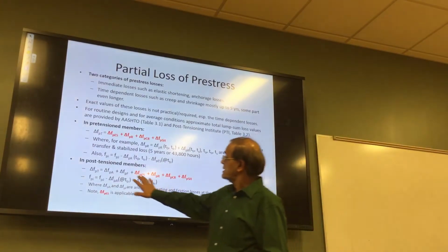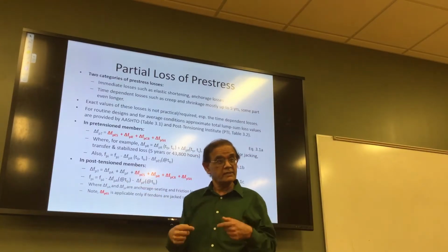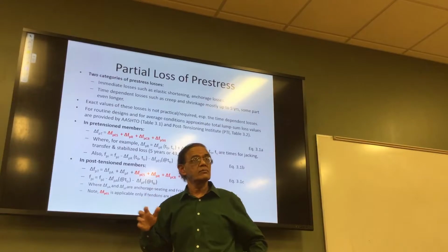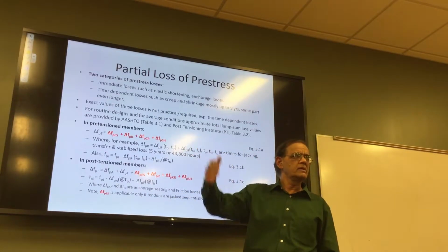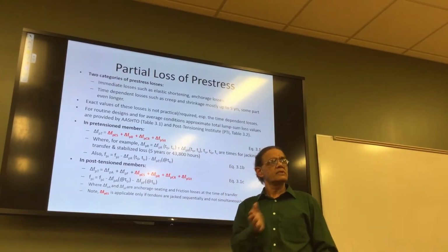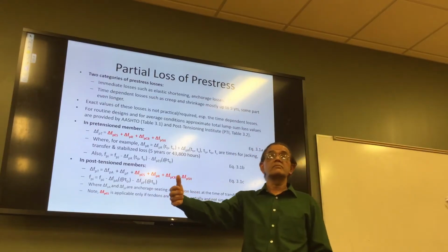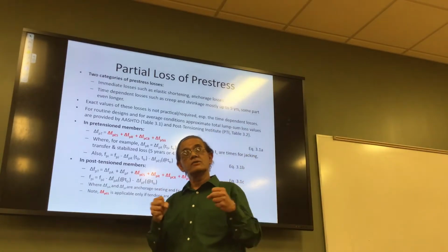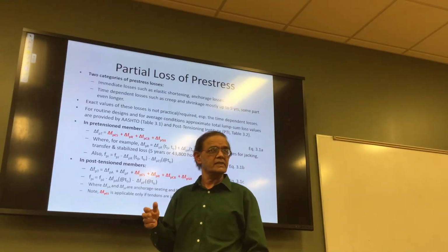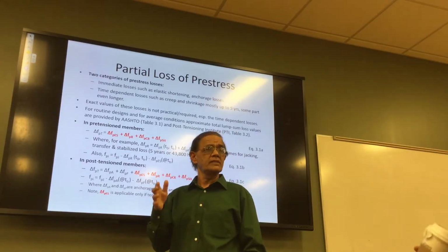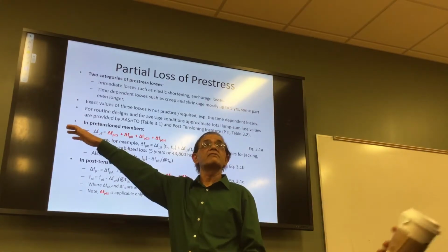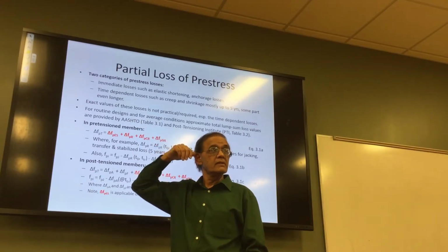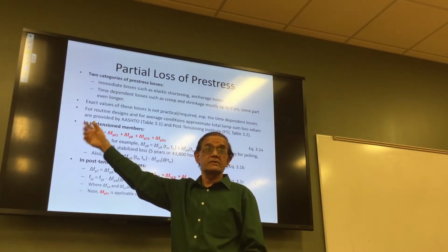Then the next thing is the post-tension members, where you have a duct and you have cables or bars that are going to be tightened at a given time, after waiting for a longer period. Because you cast the beam somewhere, then you transport it over the top of the abutment, then you have this duct ready to go, then you put your jack, then you pull it. So it takes time, all this takes time. And you don't know how long the beam has been waiting. It may have been cast in a factory somewhere and you bought it. That's possible too, if it is not too big. So it may be weeks and months even, right?